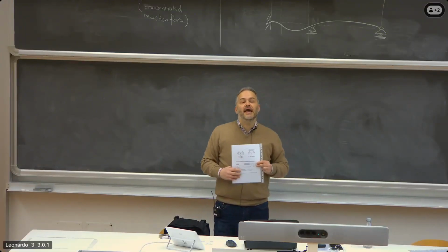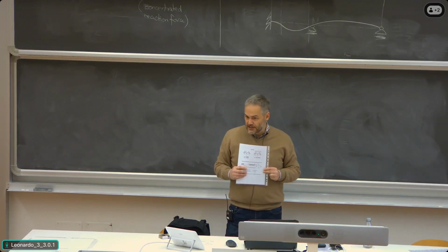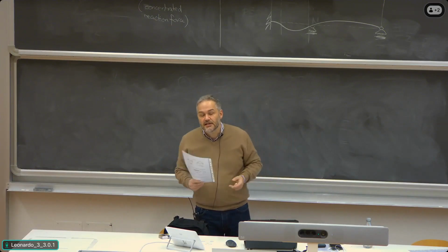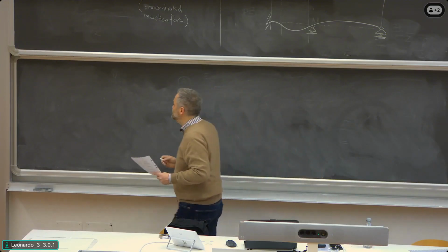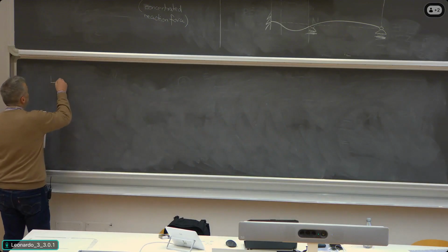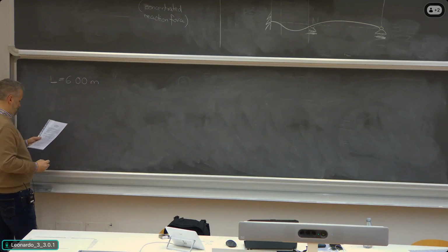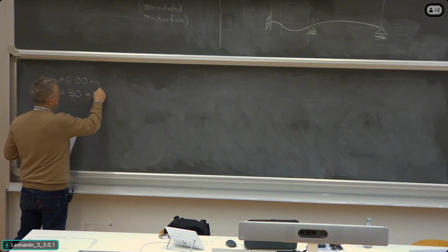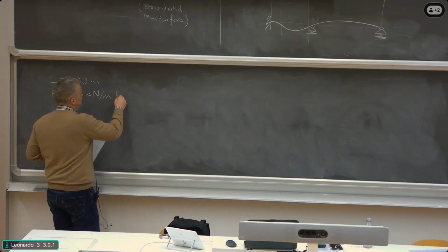So this basically ends the first part of the assignment, where we have to deal with the structural analysis part, and as you saw, it's all symbolic. Now, the second part starts, the design part. So, design and assessment. So there were some data given. L equal to 6 meters. P equal to 30 kilonewton over meter, and we specify that this is a load at ultimate limit state.